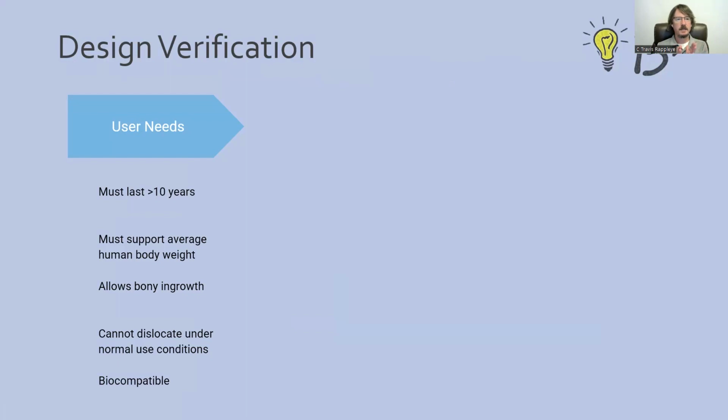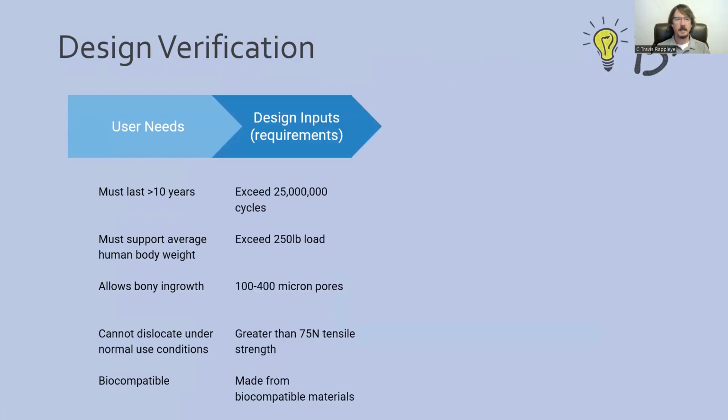And then the next step is something that I think just across the industry we could do a better job at explaining and getting down, and that's something called design inputs. Another way to word design inputs is design requirements, and this is just taking our user needs and putting numbers on them. Wherever those numbers come from, it's a variety of places again, but we'll have our list of user needs, and from that we establish design inputs, design requirements.